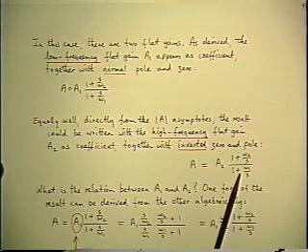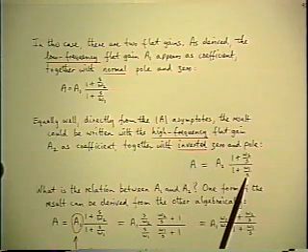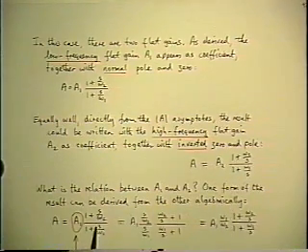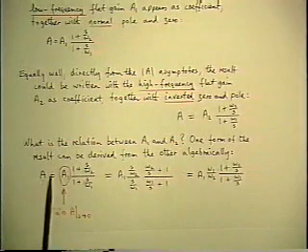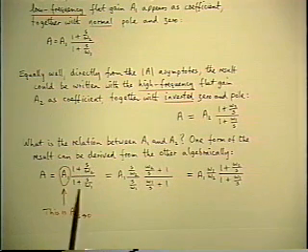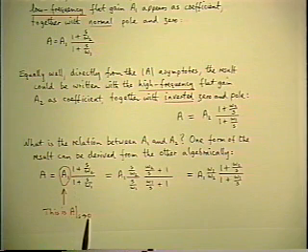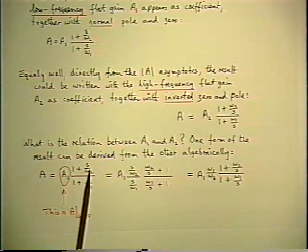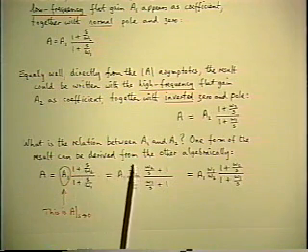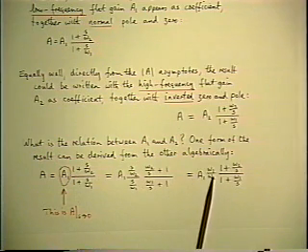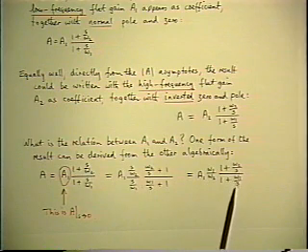And obviously they're the same thing, and algebraically they must be equivalent as well, so you can get from one to the other, which is easy to do, as you see lower down in the picture. If we start with the original expression we had this time, the interpretation of the A1 is it is the gain as frequency goes to 0. And algebraically, we can pull out S over omega 1 from the denominator, S over omega 2 from the numerator. The S's cancel, collect the terms together, and you get a new coefficient in front, and the pole and the 0 have now become inverted.